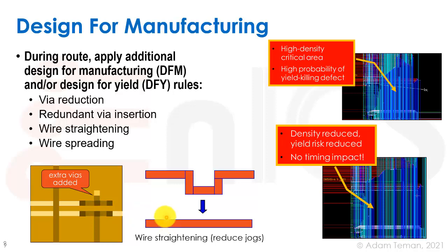Okay, wire straightening. This whole maze routing thing is an iterative process, especially fixing DRCs. Things are ripped up and rerouted, and we often get weird types of routes that you can't understand why the tool did. In this case, we have this weird jog over here, and there's no reason for it. So if we look at it again with a clean eye and say, whoa, there's no reason to do that, we can just straighten this, and that really improves everything. It improves the RC of the net, but it also improves yield, because these types of bends are not healthy, as they can be missed with all kinds of misalignment and so forth. So just straightening this is a real improvement, and there are lots of these options that occur after routing millions of wires. Okay, so that's wire straightening.